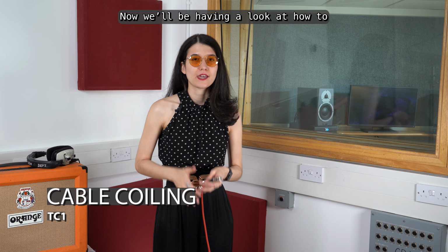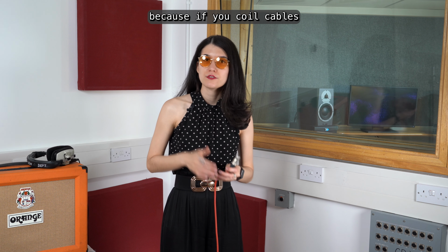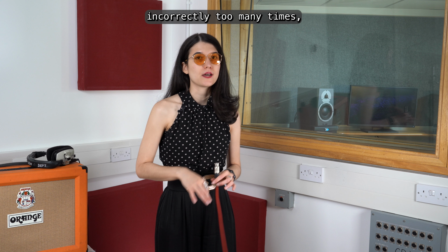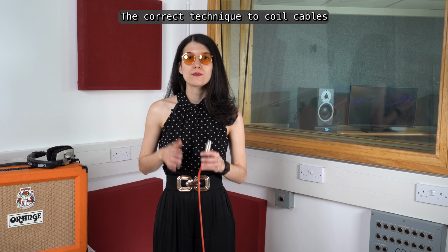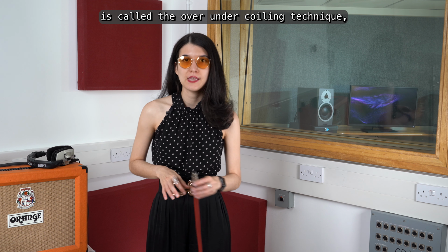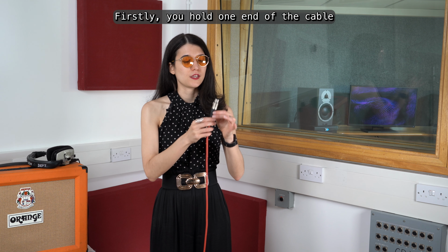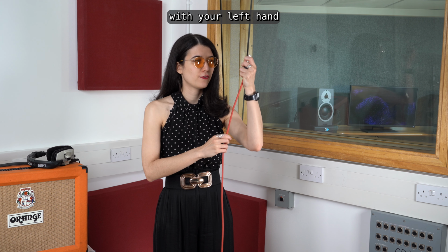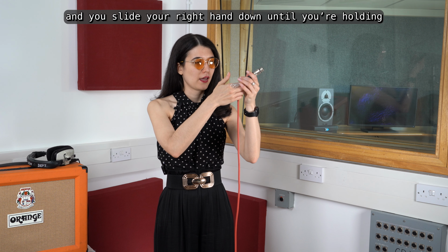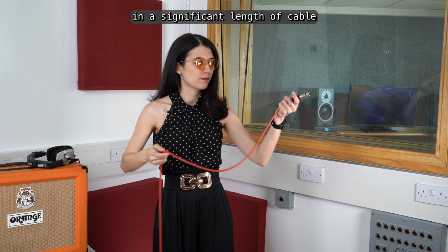Now we'll be having a look at how to coil cables correctly, and it's important that you do so because if you coil cables incorrectly too many times they may get damaged. The correct technique to coil cables is called the over-under coiling technique, and I'll be demonstrating one of the ways of doing it. Firstly, you hold one end of the cable with your left hand and you slide your right hand down until you're holding a significant length of cable,